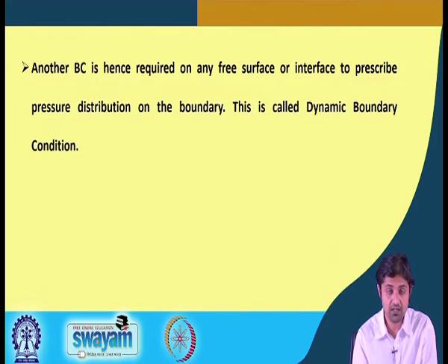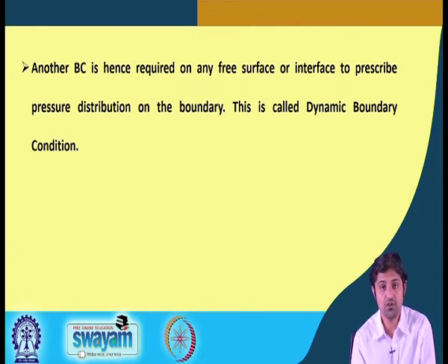So, you see we started from the boundary conditions, we went to the kinematic boundary condition where we saw the bottom boundary condition and kinematic free surface boundary condition. But one typical thing with free surfaces is that they cannot support pressure variations across it, unlike the fixed surface. Therefore, another boundary condition is required, that is called the dynamic boundary condition.